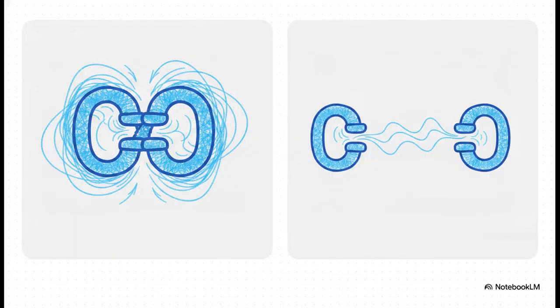This concept pulls the physics straight into hands-on engineering. Take radio work, for example. You have to deliberately choose between tightly coupled coils for maximum energy transfer, meaning placing them right on top of each other so K is super high, or loosely coupled coils for specific frequency tuning where they are deliberately spaced apart so K stays low. The actual physical, spatial arrangement completely changes your electrical outcome.